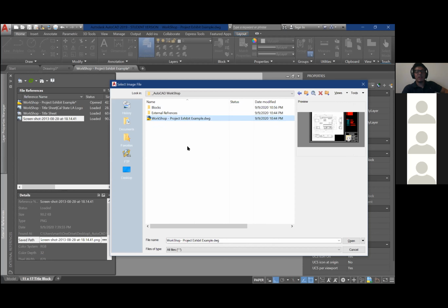this one. And what that does with this small project, it doesn't do much. But with larger projects, this one's 43 kilobytes, sometimes you'll have drawings that are reaching half a gig or almost a gigabyte of just straight data in there. So you want to break those up so each drawing is separate, and you can pull them all together using external references into one drawing. That's going to save you a lot of memory, have your computer crash a lot less, and it's going to save you a lot of time.